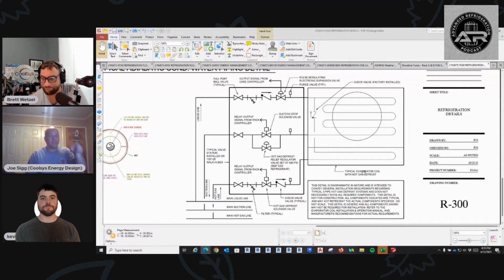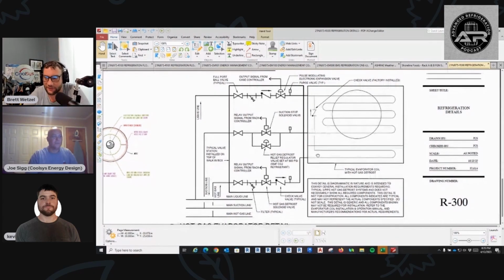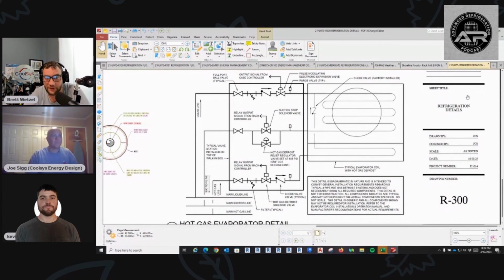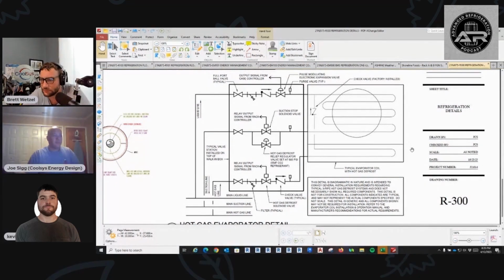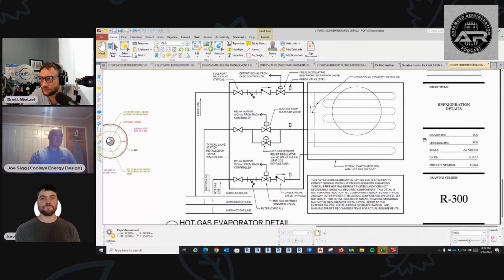So this is an essential item when you're doing hot gas defrost. This is exactly like a lot of industrial systems I've seen, where they usually have that Hansen regulating valve where it has 2 different solenoids on it. Yep. One for positive closing, one opening up, 2 at the same time or something like that for regulation, and then the other one's for a fully open option. Correct. Yeah, wide open feature. Yep. So that's basically where we're at.